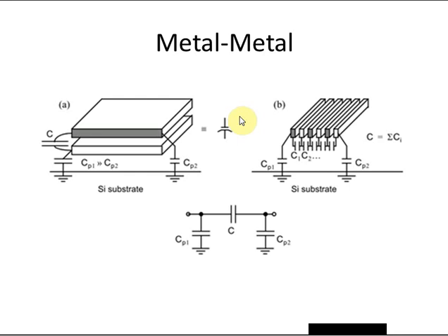So that's being done, but one individual metal capacitor on its own is not a varactor, and because the oxide layers that separate neighboring conductors are not as thin as the gate oxides, which again can be as thin as a nanometer or even less. So the capacitance density is typically not going to be as high as using a MOSFET. Now, in fact, in modern processes, these capacitors can have a capacitance density almost as much as a MOSFET because you can stack so many of them on top of each other.